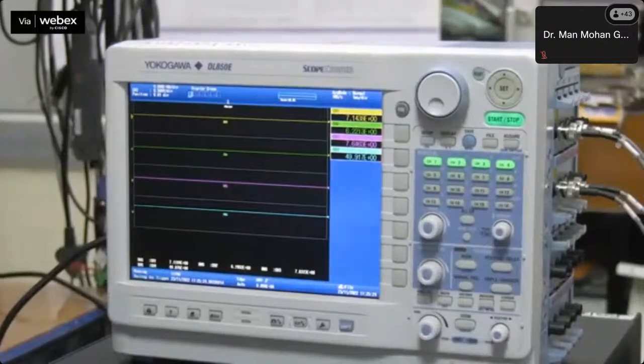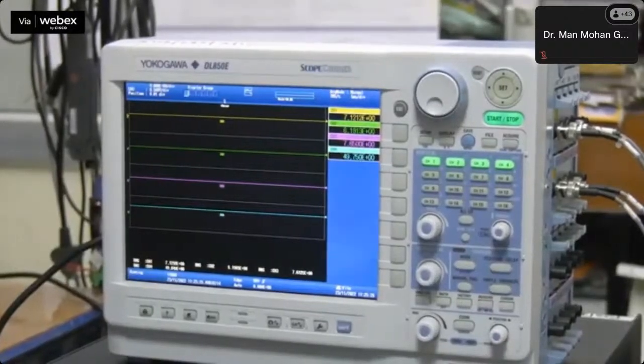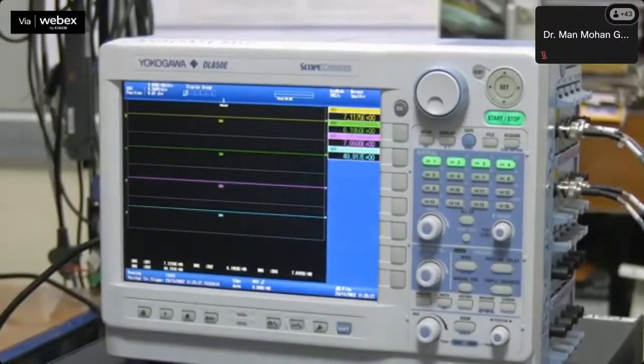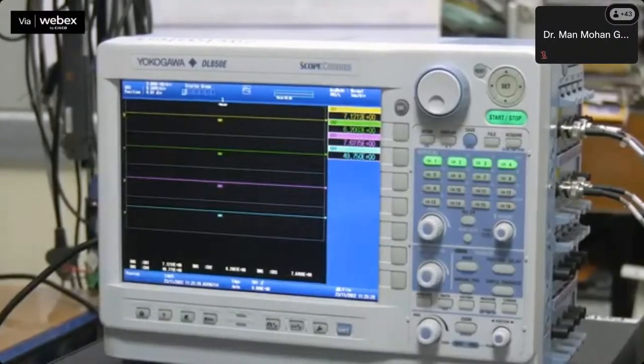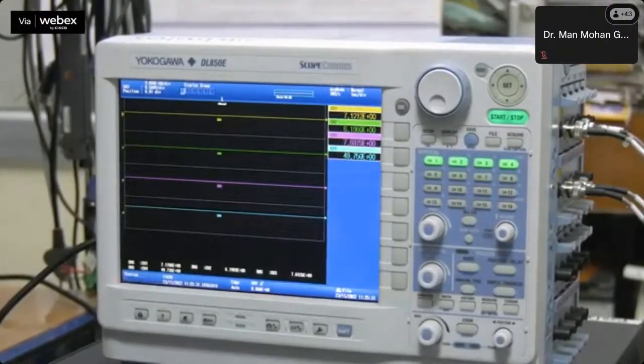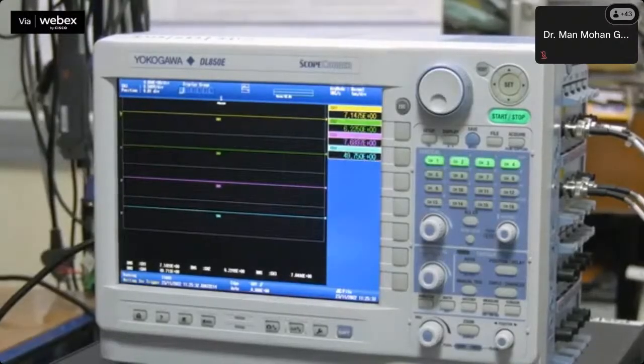The initial DC bus voltage is taken as 270 volt and then it is changed to 300 volt and 260 volt respectively. It can be observed from the DSO that the change in DC bus voltage does not affect the battery voltages or currents and the DC bus is perfectly regulated.